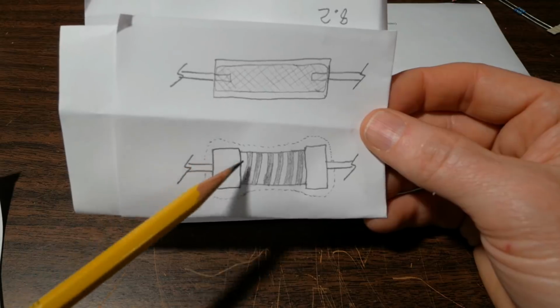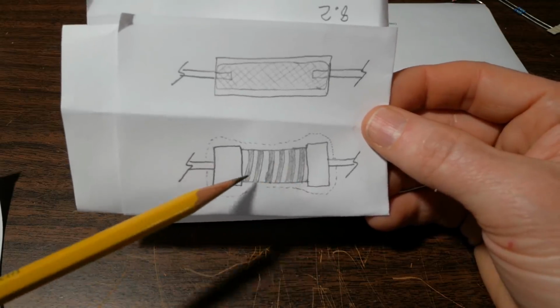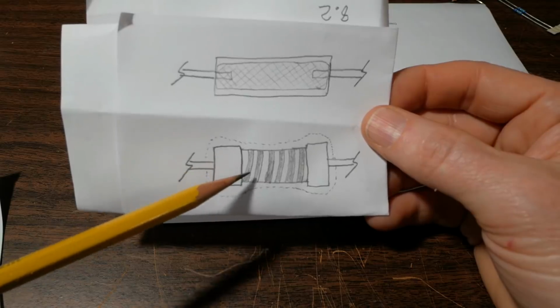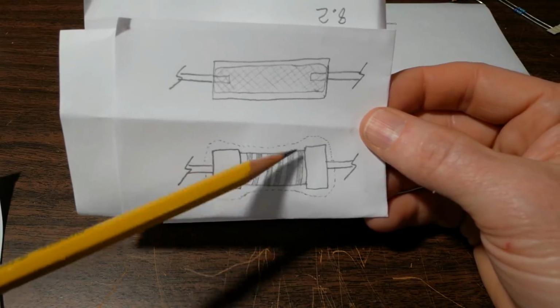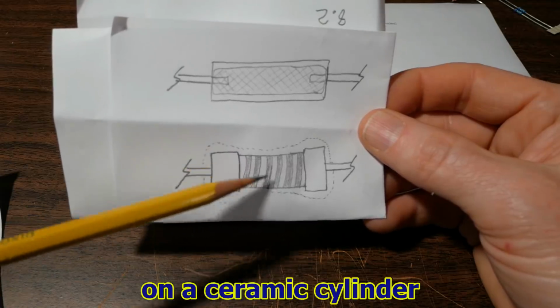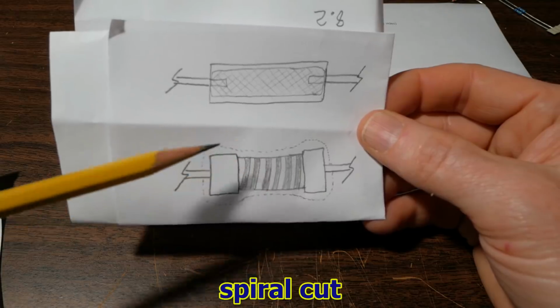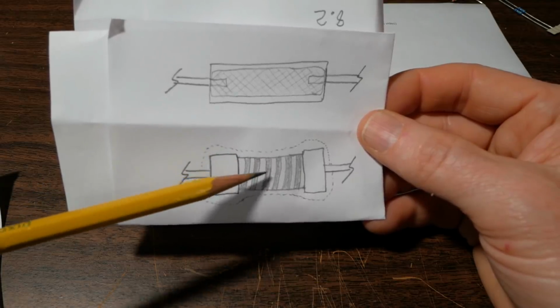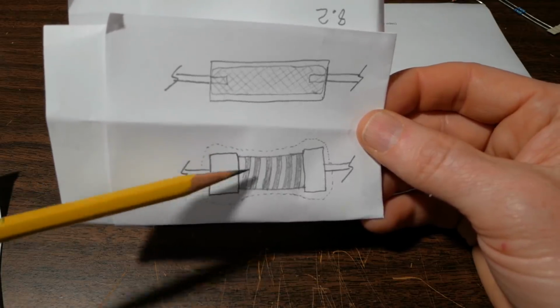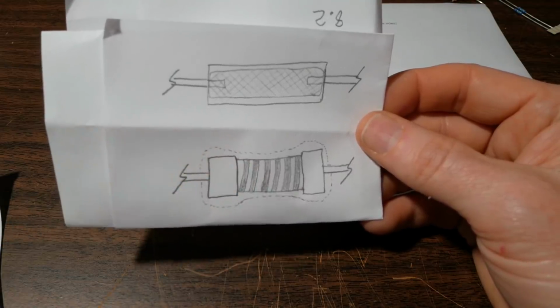You have two metal caps here on each end, and what they do is they put a thin film of carbon here, and they cut away strips of this, so you end up with a spiral, and depending on the spacing and how many turns, you end up with your given resistor value.